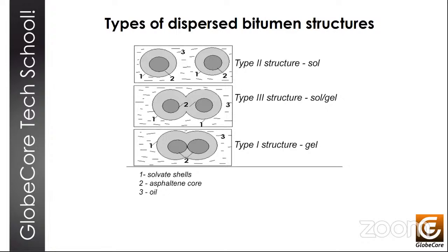Type 1 bitumens have low resistance to oxidizing factors during processing and the production of asphalt concrete. The advantages of type 2 bitumen are high cohesion and deformation resistance in an elastic viscous state, increased resistance against oxidative factors that cause aging. The disadvantages are lack of elastic and elastic plastic states, low heat resistance, and poor water resistance. Residual bitumen mainly belongs to this type.